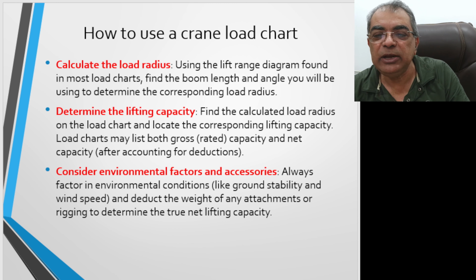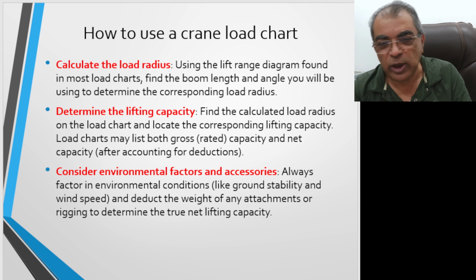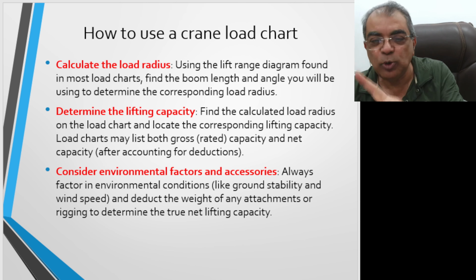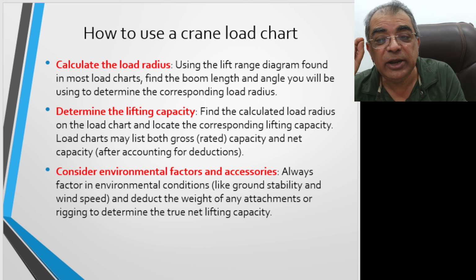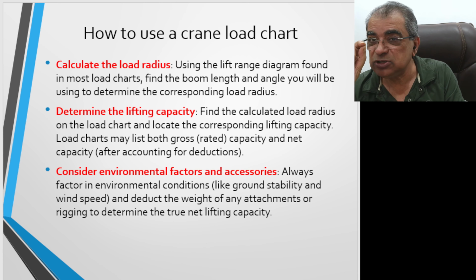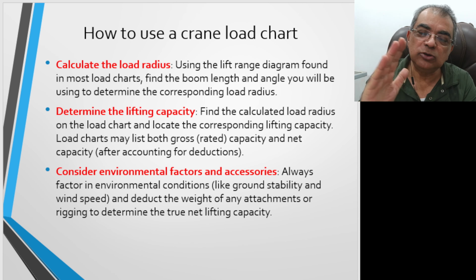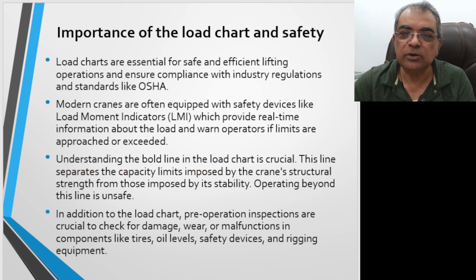The load chart may list both gross capacity and net capacity. So you have to check the gross capacity; it is written, both are written. And consider environmental factors, because this is very important. As I have explained in one of my videos, wind speed can have an impact on the load and the boom. So if you want to know, you can watch my video on this subject.